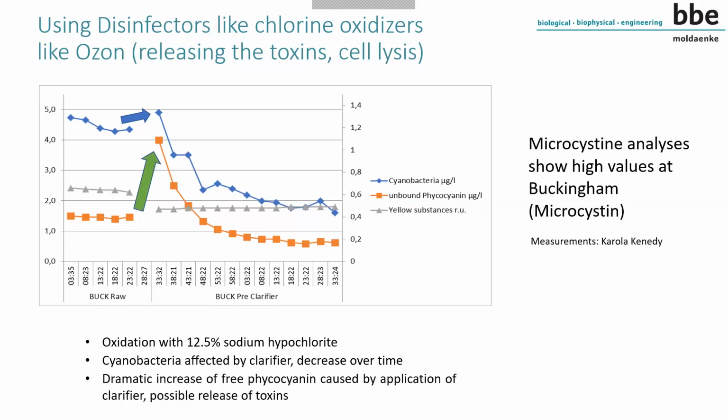Okay, and like always, the same question: what is the accuracy of measurements? It's 0.01 microgram per liter. But if you measure at this low concentration, the fingerprint situation is not that perfect anymore, but the minimum is 0.01 microgram per liter. This is for total chlorophyll A. Total chlorophyll A. Yes. Okay.